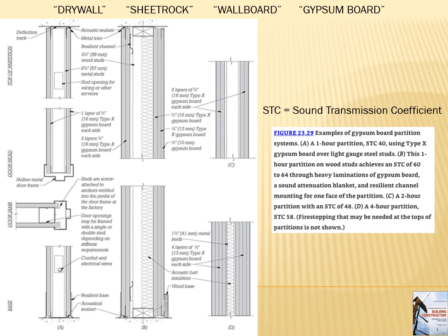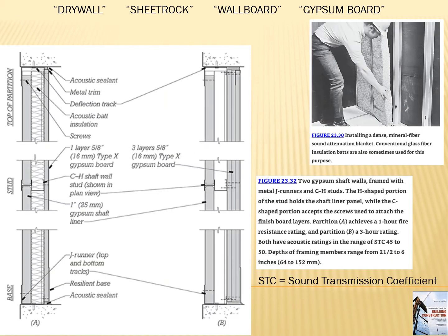Some specifics about what you can do with drywall. Wall sections is you can regulate the sound transmission coefficient. There's different ways of doing that, putting insulation in the wall, and the air gap, and several layers of sheetrock. You can change the sound transmission.